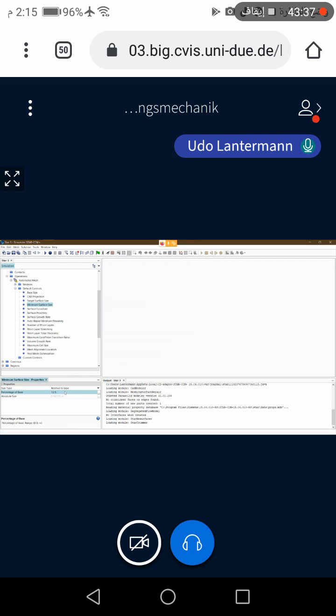Every other parameter we set in this mesh is relative to this base size. This is an advantage: if you have to change the base size, you don't have to change every parameter. You will only have to change the base size, and every parameter will be on the same level as before. If you use absolute values, you have to change every length parameter of your mesh generation. If you choose this relative size, then you only have to change your base size, and that's it.